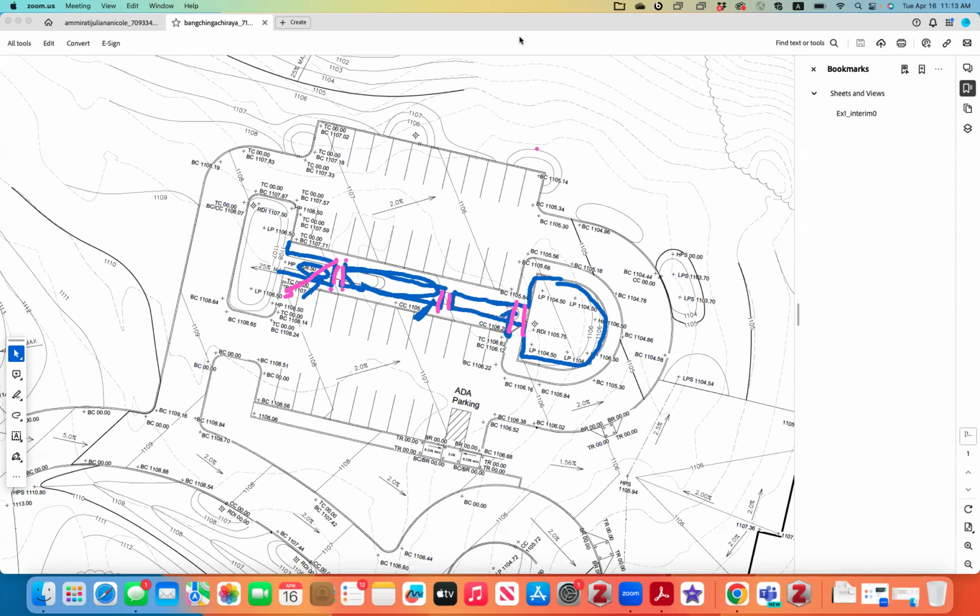For the sidewalk in between, if I end up doing that, do I need to label it? You mean label the sidewalk? Yeah, like the paint, the area in between. No, you don't need to. You basically outline the shape of that sidewalk, but you use all the spot elevations to indicate where it goes. Okay, this is my sidewalk design, and people will understand. Yeah, okay. All right, so that is about the sidewalk.